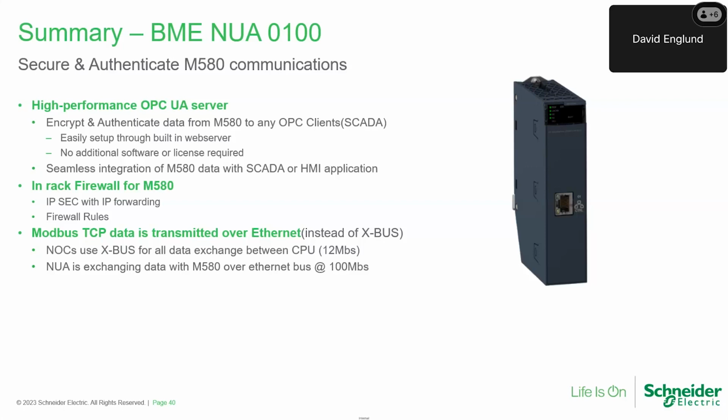We can simply manage the OPC UA server and its cybersecurity functionalities via the embedded web server. This eliminates the need for any additional software or licensing. And the BME NUA also increases performance when used for Modbus TCP data, as it uses the Ethernet backplane instead of the XBus.